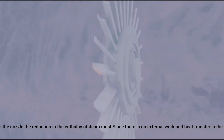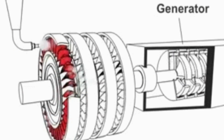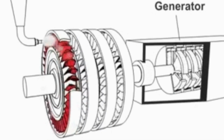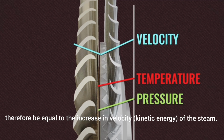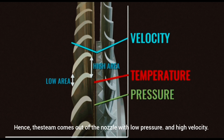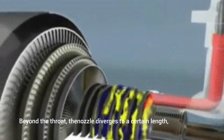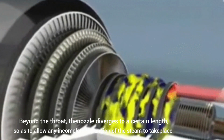Since there is no external work and heat transfer in the nozzle, the reduction in the enthalpy of steam must be equal to the increase in velocity, or kinetic energy, of the steam. In other words, the steam performs work upon itself by accelerating itself to a high velocity. Hence, the steam comes out of the nozzle with low pressure and high velocity. Beyond the throat, the nozzle diverges to a certain length, so as to allow any incomplete expansion of the steam to take place.